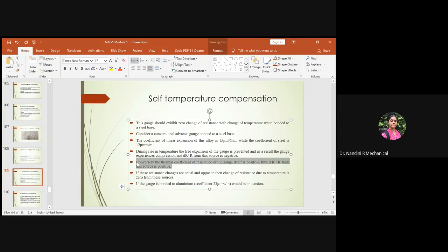You won't get any negative value here for the change of resistance, because it is not expanding at all. It is not showing any response to the external environment. So the material, the device that you have developed, is itself capable enough to overcome the compensation with the temperature,